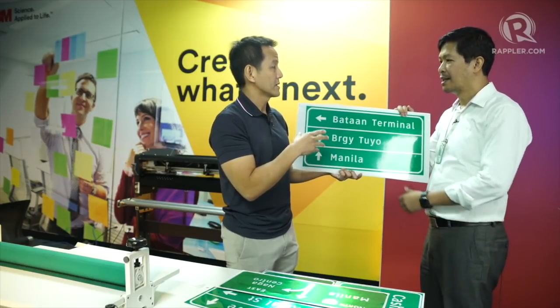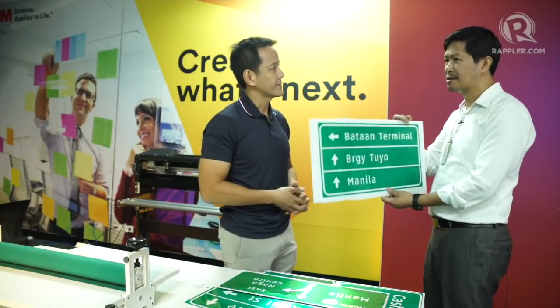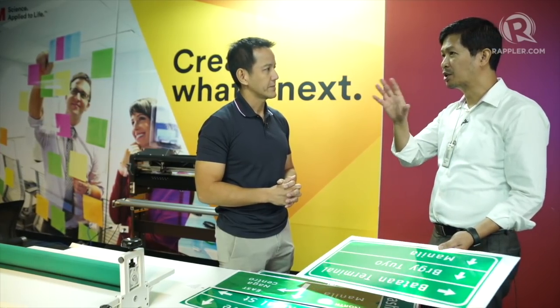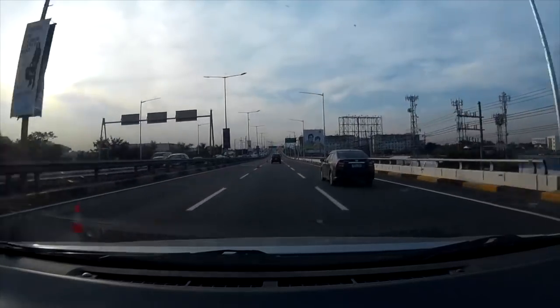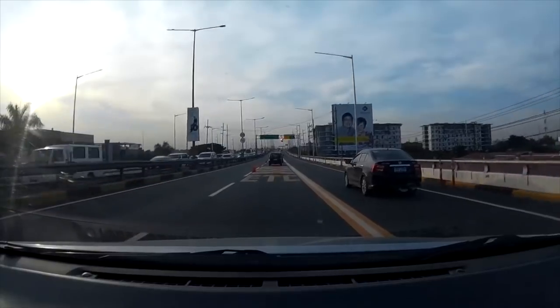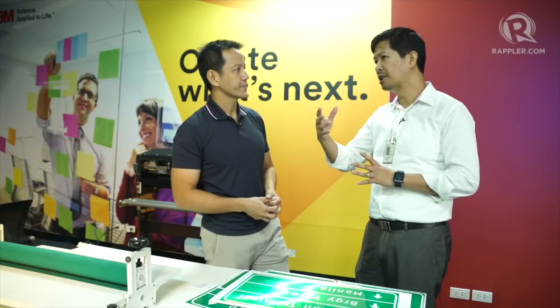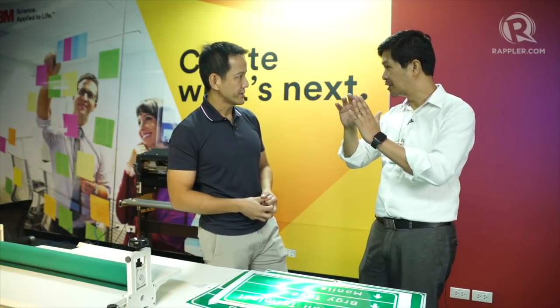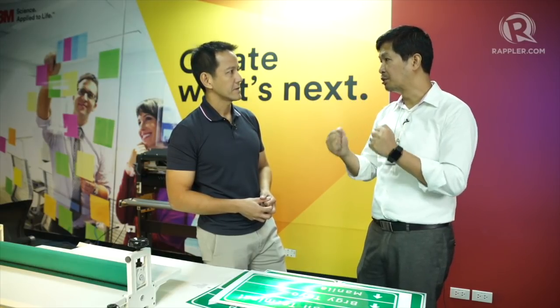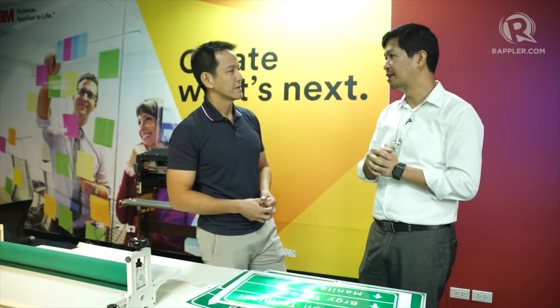Now, as the road gets faster, you need more time to read what's in front. For a typical 80 kilometers per hour speed, you would want a distance of 300 meters. This is where you start to see that there's a sign. At 200 meters, you start to distinguish letters, able to read. And at around 100, you start to react to that.